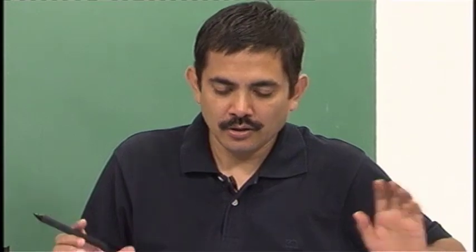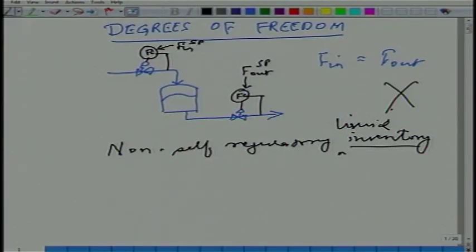Is that clear? So what that essentially means is that we will have to have a level controller, and that level controller sets this set point. Alternatively, the flow in set point sets the flow through the process, flow through the tank. So F in is the throughput, what is flowing through the unit. That is the throughput through the unit, and then you have got a level controller.